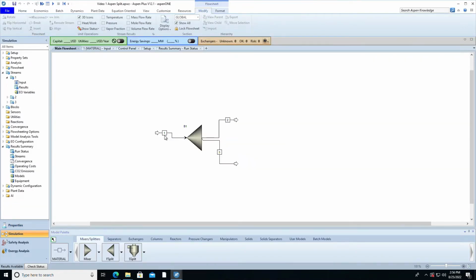So now that we've run the simulation, you'll be greeted with your main flow sheet. There is also a video on this that is linked in the Google Doc. I already have my splitter set up here. However, there is an example in the PDF, and in the Google Doc there is a YouTube video linked. The reason why we're using a splitter is because a bubble, dew, or flash calculation can be performed on any stream, but Aspen Plus specifically requires some unit operation to be present, and a splitter is one of the most simple unit operations we can do within Aspen.